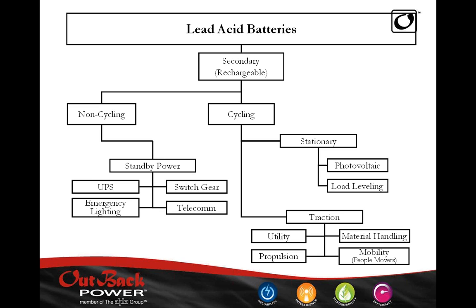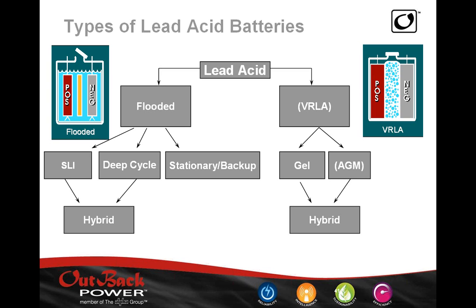And so if we use a battery that's designed for very good floating applications, but not very good cycling applications, then we're going to misapply that technology and have problems down the line. On the other hand, if we use a battery that is meant for a very high level of use in terms of everyday cycles, and we choose a battery that's designed for float, that again is going to lead to some problems. So it's very important that we apply the right technology to the application.